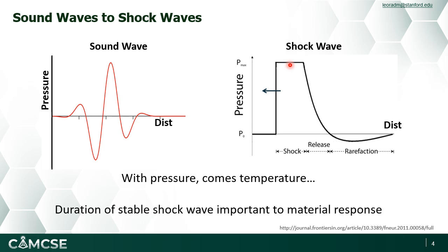Similarly, it's important to understand that the duration of this stable shock wave is incredibly important to understanding the material response that ultimately happens. If we end up with no duration of stable shock and it decays immediately, that's called a decaying shock. And that ends up with quite different properties than a stable shock, which in itself is different based on the duration of the stable shock, from nanoseconds to microseconds in some cases.